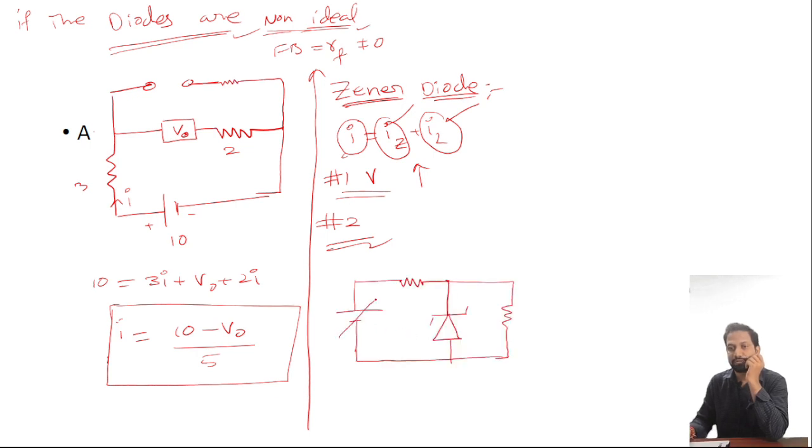Say this is a variable supply, and it can be varied from 40 to 120 volts. Minimum value 40 and maximum value 120. The Zener voltage is 30 volts, say, and the load resistance is 1 kilo ohm, and the series resistance, say 1500 ohms.